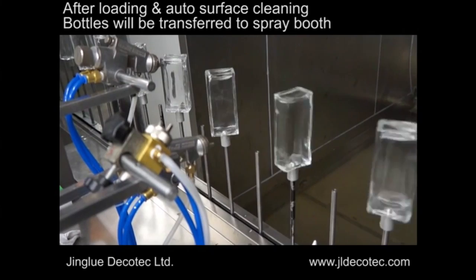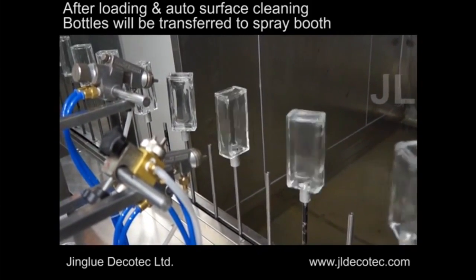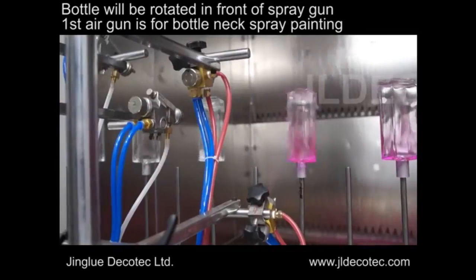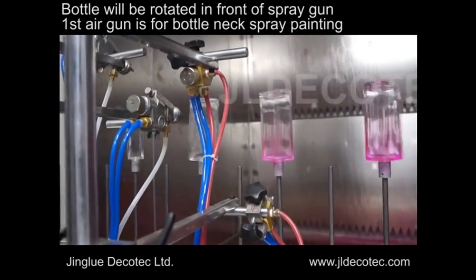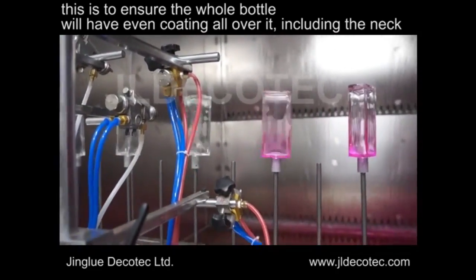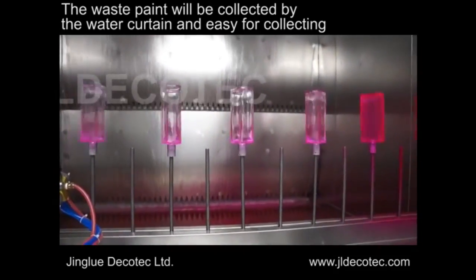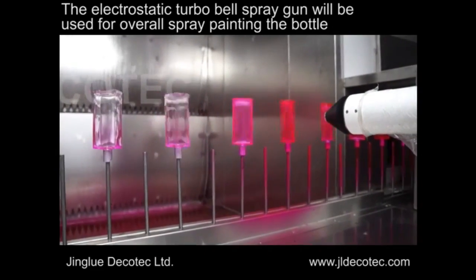Painting. As required to prevent rust or for cosmetic reasons, some of the components are painted. The parts are hung on a small rack, set on a conveyor and passed by a spray nozzle. Some automatic painting operations employ electrostatic spraying, wherein parts and paint are electronically charged. The paint and the parts are given opposite charges. For instance, the paint will be given a negative charge while the part would be given a positive charge.